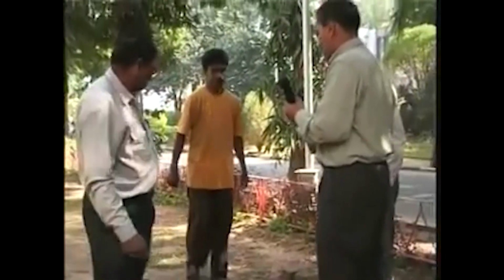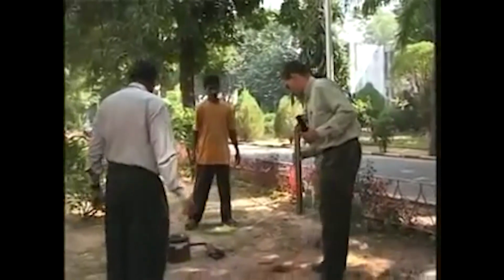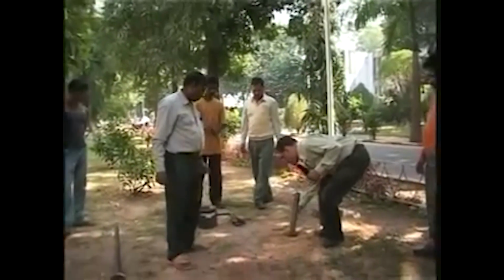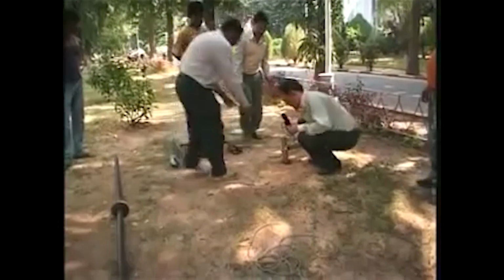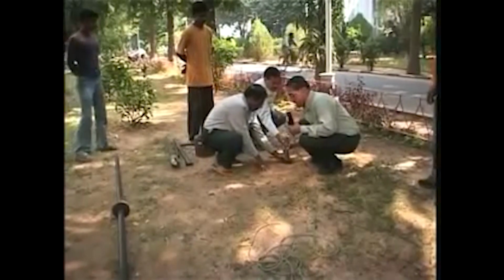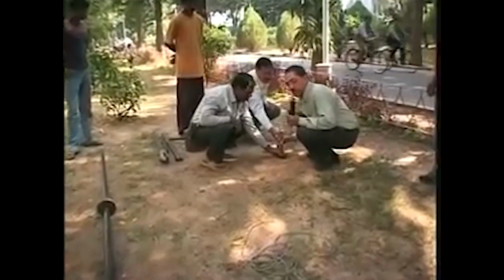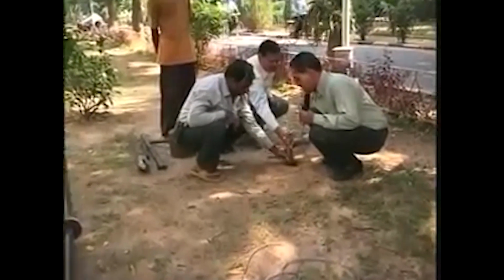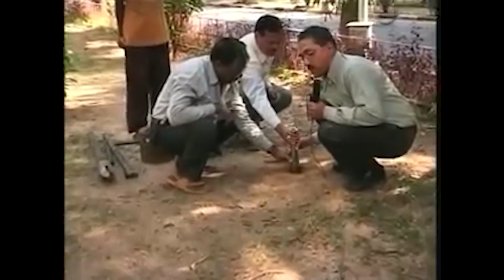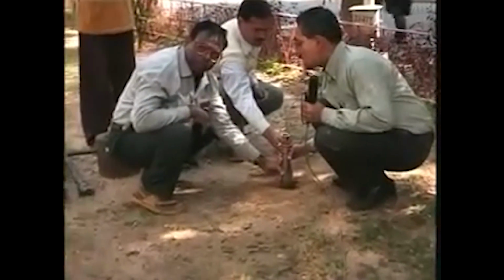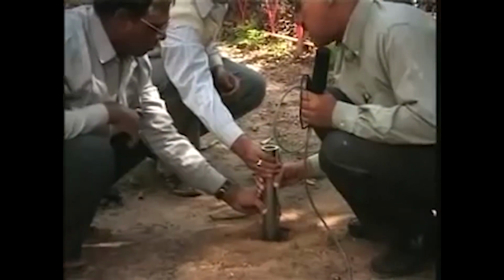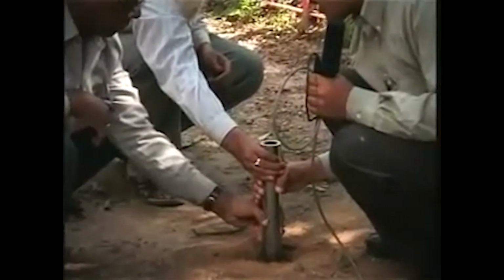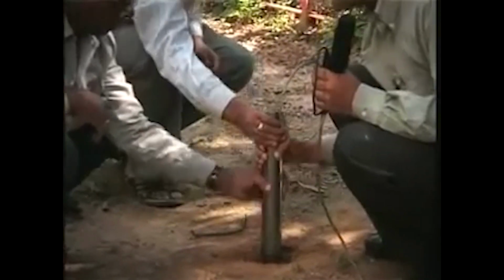And what we are going to do, we are going to drill a hole in the ground, and we just lower the sampler to the depth drilled and drive it, connect it to the SPT hammer with the standard rods, and drive the assembly with the standard SPT hammer, as you are going to see in the next little bit.